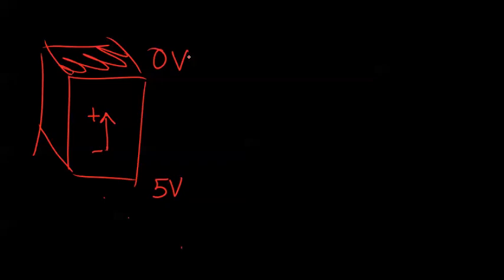What direction is the electric field? From negative to positive, or from the lower potential to the higher potential. In this case, you are applying an electric field opposite to the dipole. Therefore, the material is actually shrinking in size. So when you apply it opposite, the material gets smaller.